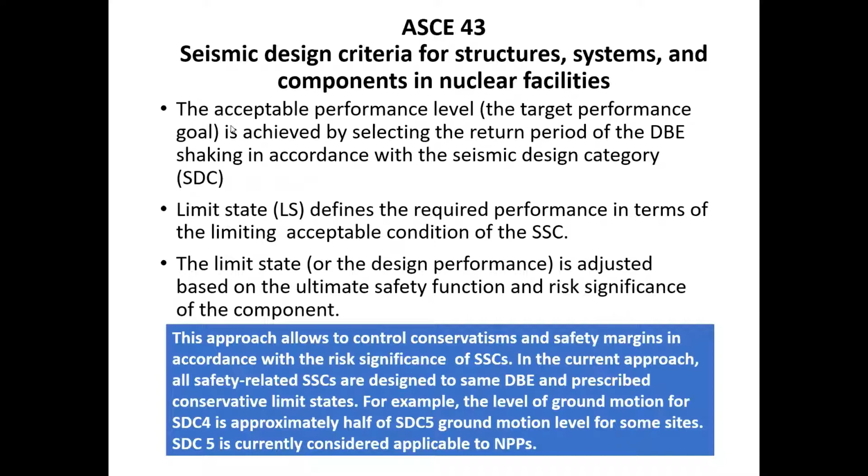So there are two basic important parameters. How do I define my design basis earthquake, what return period, and what should be my limit state for the design. Now the limit state, this is an important point I need you to understand. The design limit state is not the ultimate safety functional limit state or the fragility that you use in the risk assessment. So there is still a significant margin beyond what you design to in the traditional design process, when you use codes and standards.